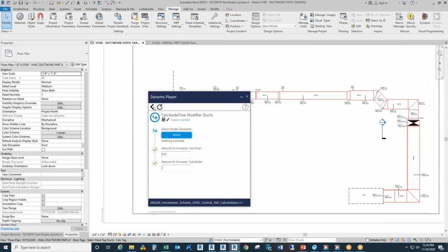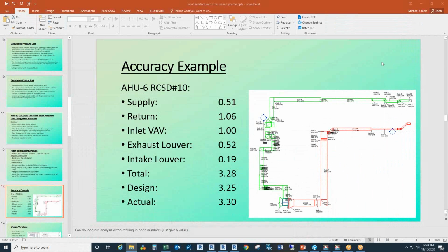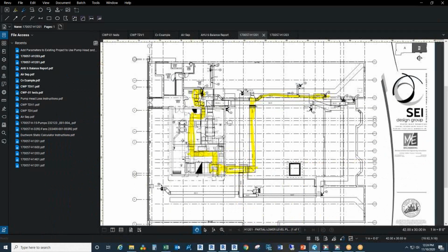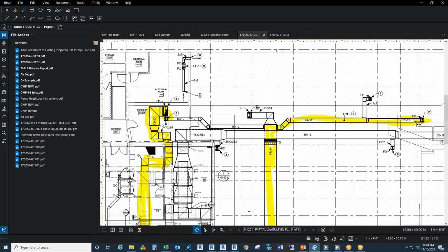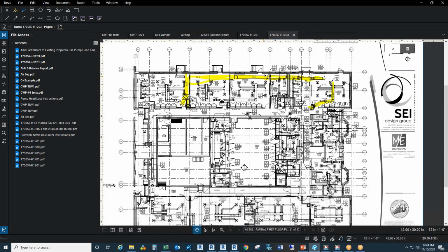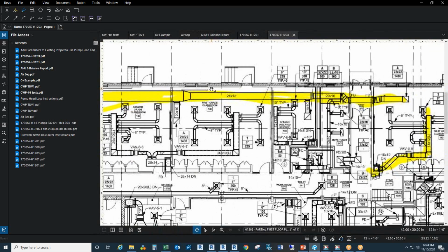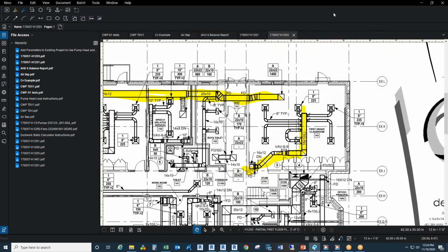We're going to look at now a comparison between an actual calculation and balancing data. So we're going to try to do this pretty quick. This system right here is this system. We start off in a basement air handler supply down through a crawl space up into a classroom. Similar with the return, this comes through the mechanical room up and onto the first floor. The return run makes its way over to the classroom, and then here's your first grade classroom.